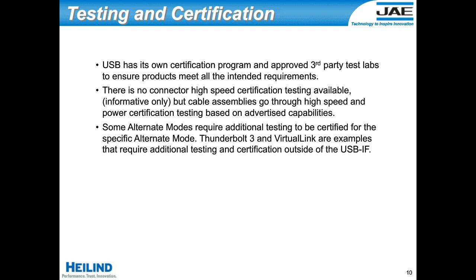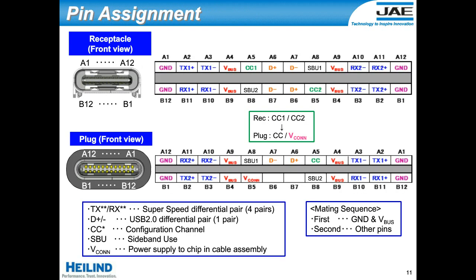And here we start to go into a mechanical overview of the actual connector itself. You can obviously see by looking at this pin layout that it is a symmetrical pin design. The V-bus and the power and the ground pins are located in positions where even if you rotate the connector, they will be in the same place.